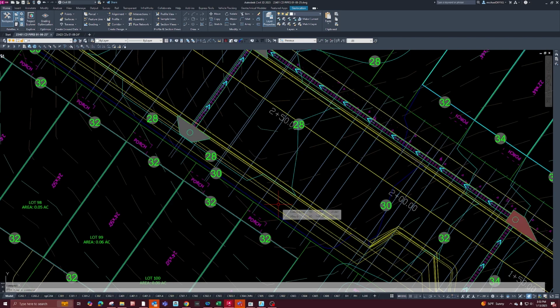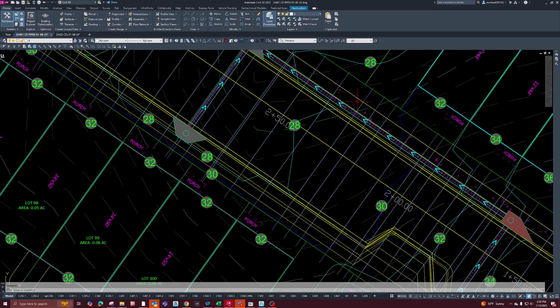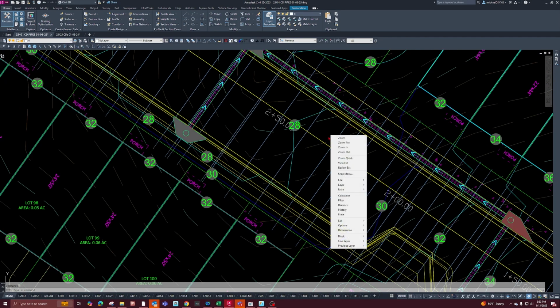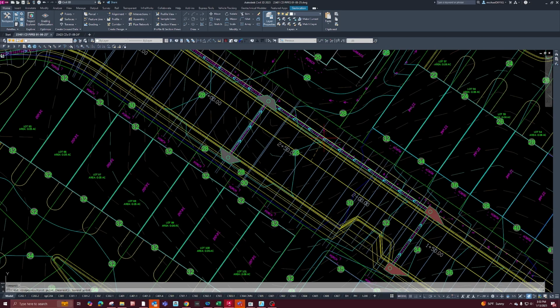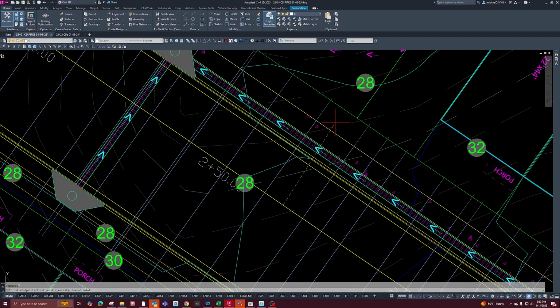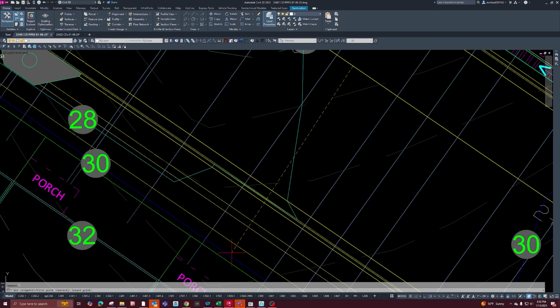So you see we want our sample line to be at least to the back of the sidewalk on each side. So if it's just from the alignment, this is going to be to the right, so we'll do 25 feet to the right, and we'll do 30 feet to the left, because that gets us to the back of the sidewalk.